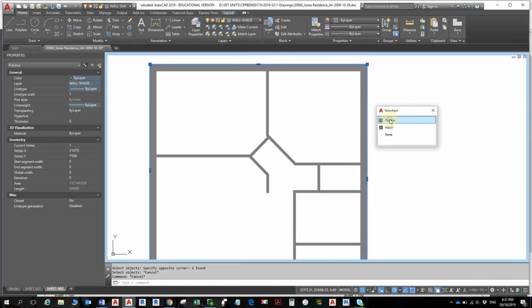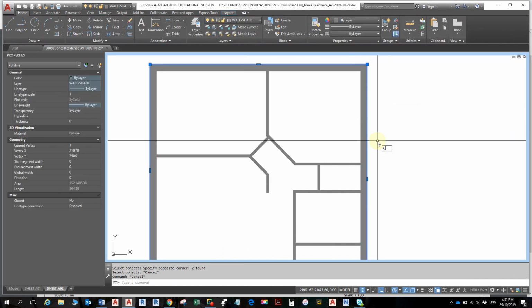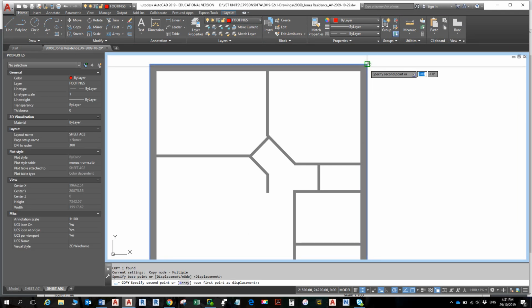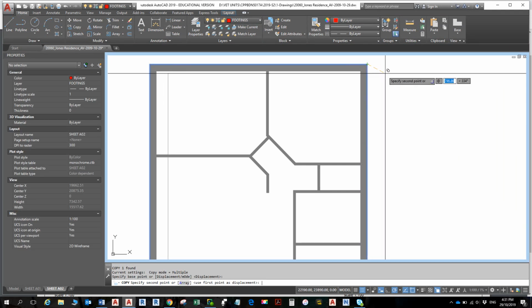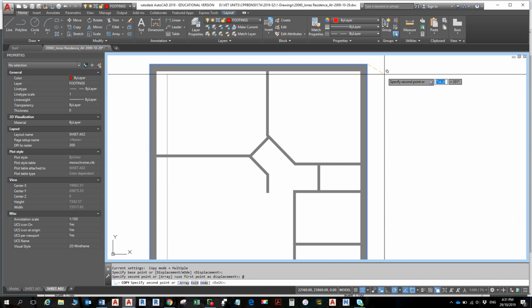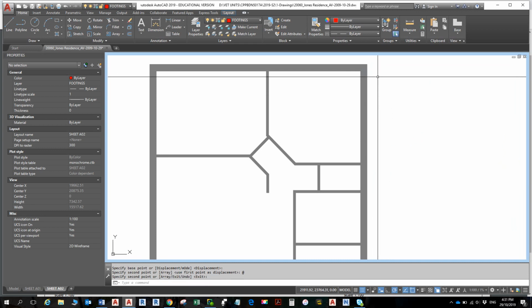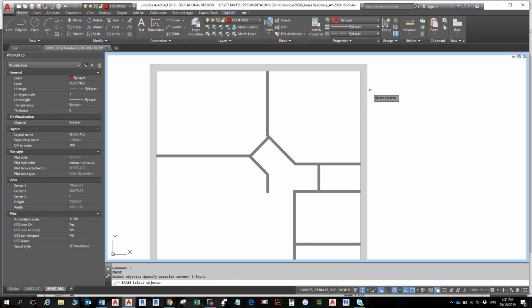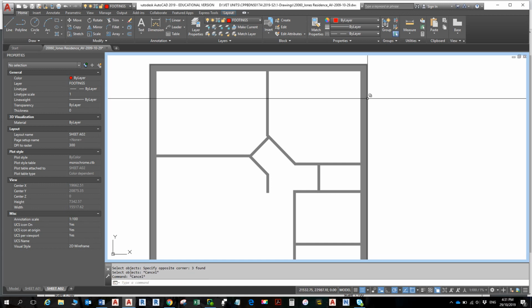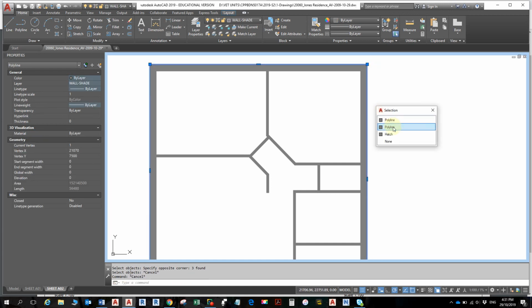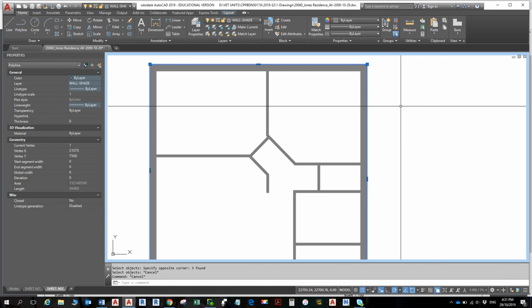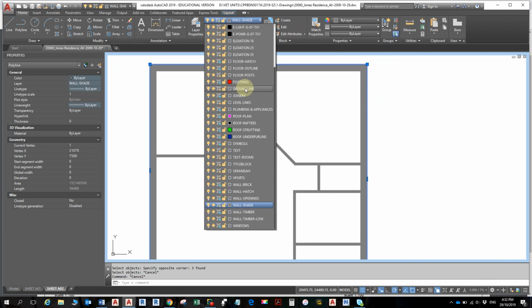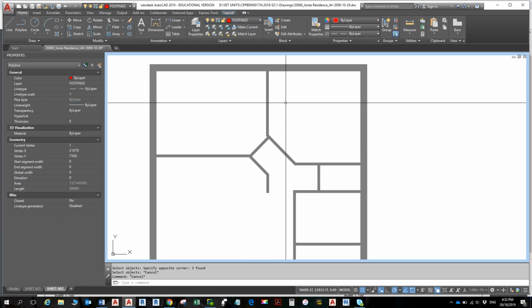All right, so we're going to pick up the polyline, and we're going to go CO for copy, and we'll copy it from here to shift @ and enter. Did that work? Yeah, it did, and enter to finish because copy repeats. There's 3 things there, 1 or 2 being polyline. So one of them, they're both the same. Just pick one of them and change that one into the footings layer.